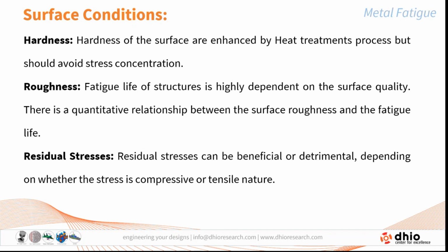We have seen that for most components subjected to fatigue load, it is at the outermost surface that the weakest grains or the weakest atoms are prone to crack initiation. Thereby, roughness plays a key role in the fatigue life of the component. So the fatigue life of a structure is highly dependent on the surface quality, and there is a quantitative relation between the surface roughness and the fatigue life.